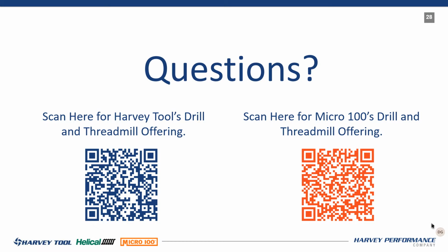So if you're making a thread with a thread mill, if you're using a multi-form thread mill, you want to stay engaged in the material all the way. So you're going to go down, you're going to stay in there. So you do degressive passes. Yeah, I think that's what that is. Degressive passes on the radial, just like we explained. Yeah, 100%.